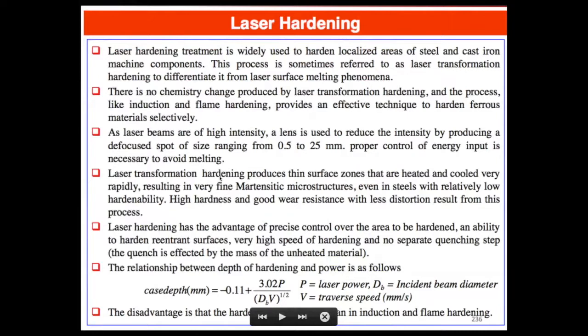You're just giving it a very high, very focused laser pulse, right? So you're doing both heating, but you're also putting in compressive stresses at the surface. This also has a peening effect as well as just a heating effect, right?